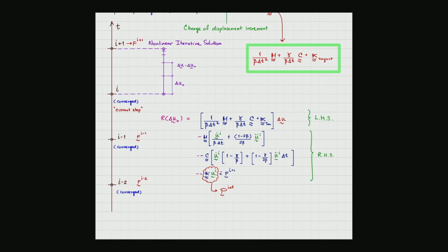If the magnitude is not high, that means okay, you might be eligible for using the bigger time stepping size and also bigger mesh size. And once you see that the input forcing function is questionable or suspicious, you expect that nonlinearity is going to be there, then you stop the analysis somewhere before